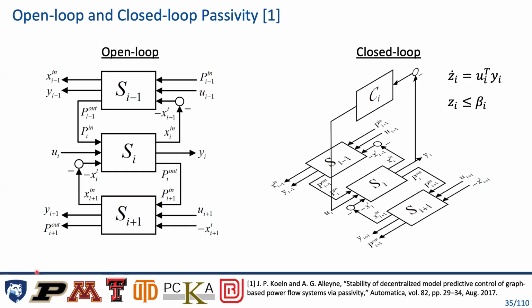From the context of MPC, ensuring passivity for MPC doesn't come for free. But if you add some type of passivity preserving constraints, then you can just build that into the series of constraints within your controller to make sure that your controller is either always passive or passive on average. And that's what this kind of type of equations would ensure, that you could behave in a non-passive way temporarily if that helps you achieve higher performance. But as long as you preserve passivity overall, then you would guarantee closed loop stability.